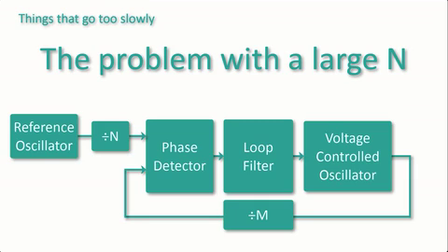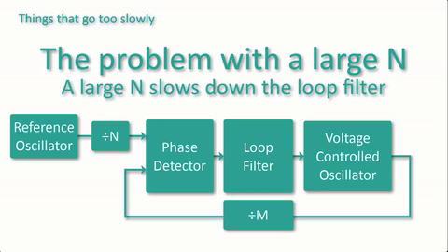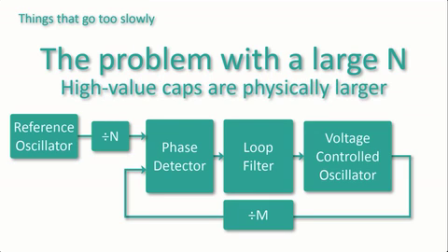Why? Because if the output frequency from the phase detector is low, then the loop filter, and remember, that's an averaging filter, has to be slow. And that, in turn, means that the loop settling time is going to be slow, and bigger capacitors have to be used, and size matters in this thinner is better world. But you know, there's another factor that isn't so obvious.